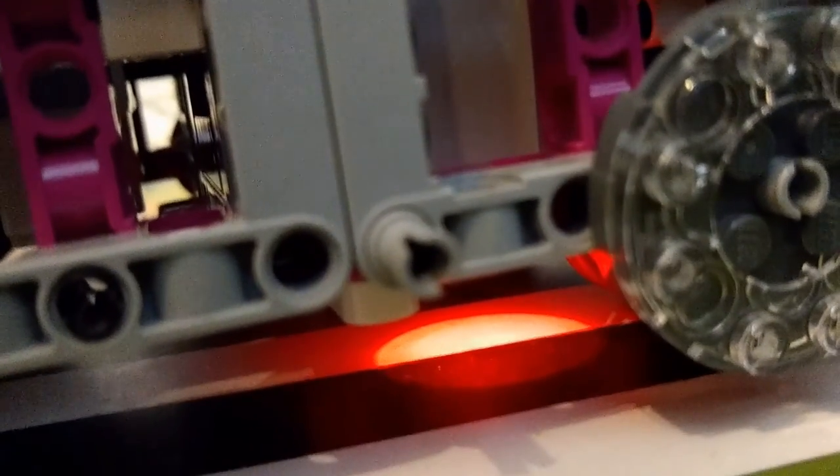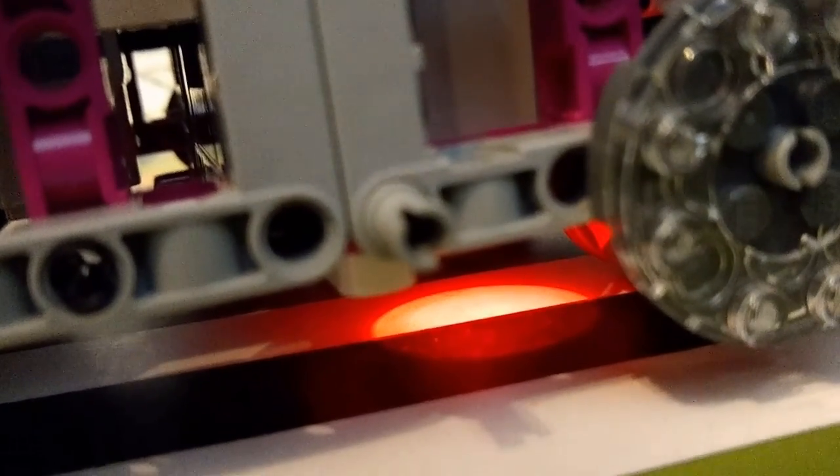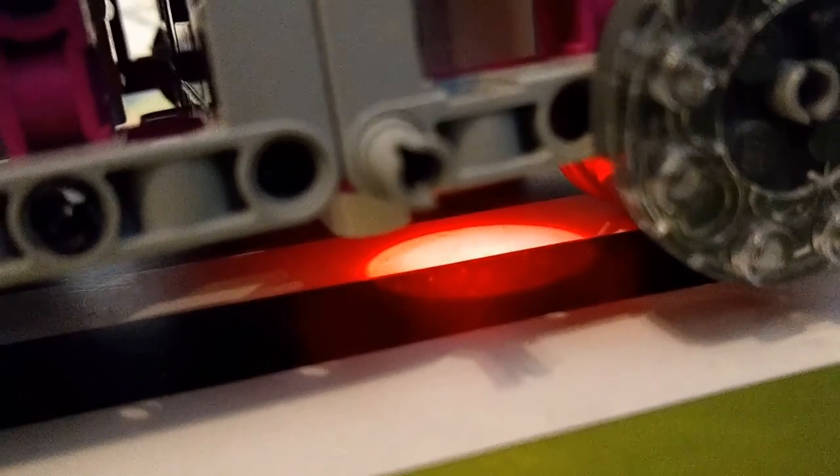The robot is going nice and smoothly, not jerking a lot, because we have a gain of 0.75, or a proportion of 0.75, meaning it's only 75% of the original value. And that is a video of proportional line following.